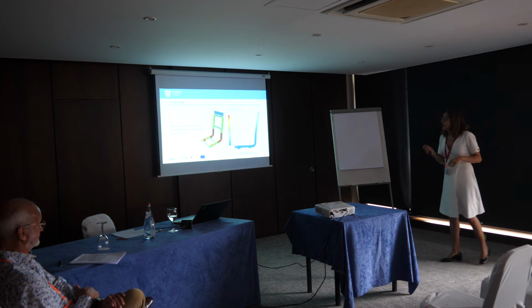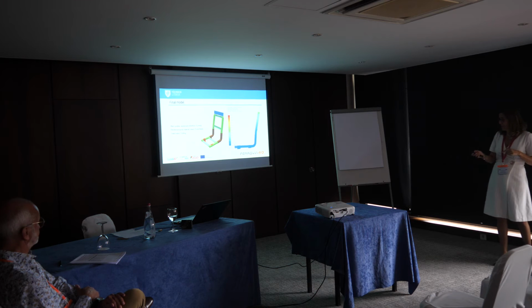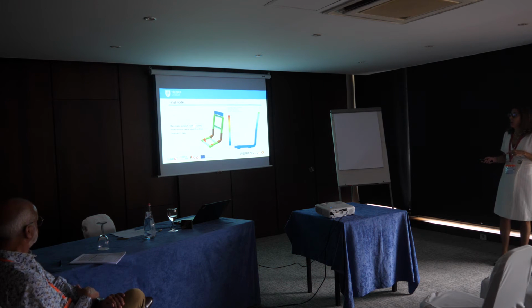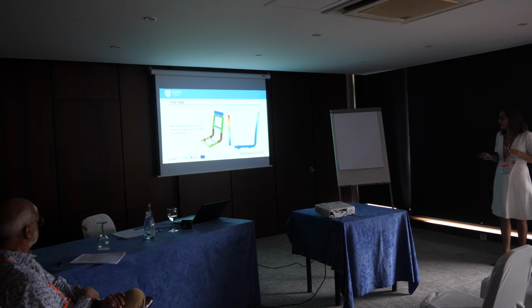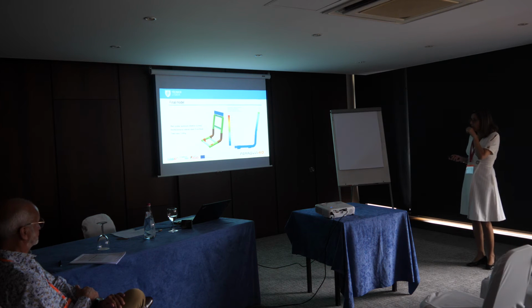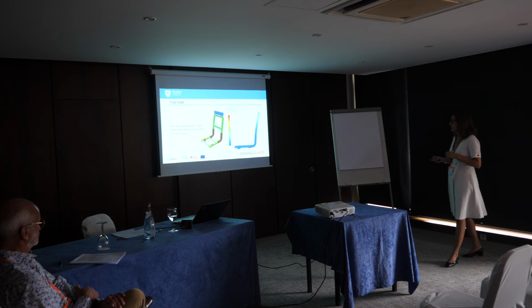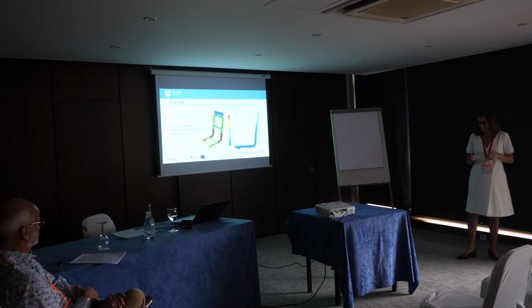What is the difference? The main profile here is not from steel, but aluminium, with 40 per 40 per 3.5 millimeters. The reinforcement material, of course, is steel, and we keep the 3 millimeters thickness. The total mass decreased by more or less 4 kilograms, and the maximum displacement was about 29 millimeters.